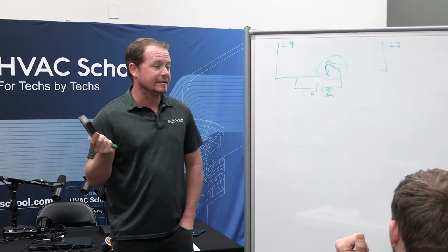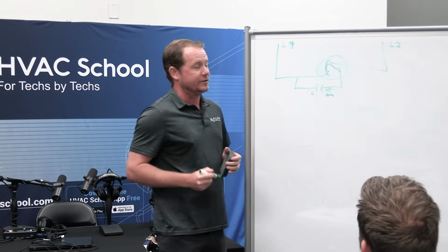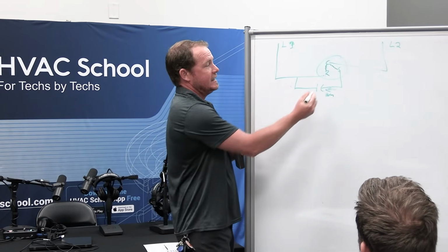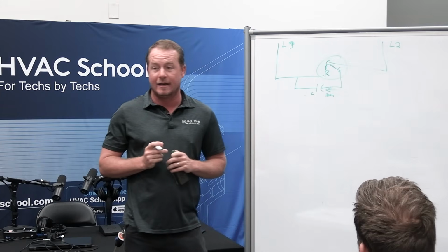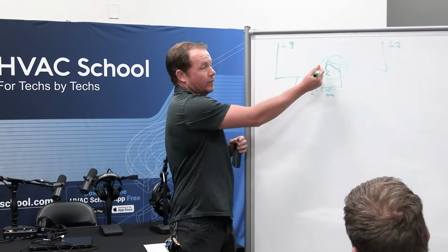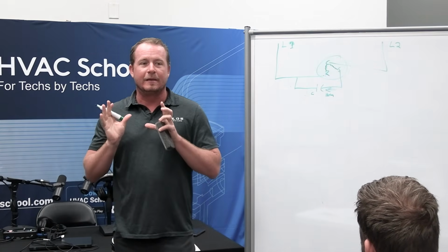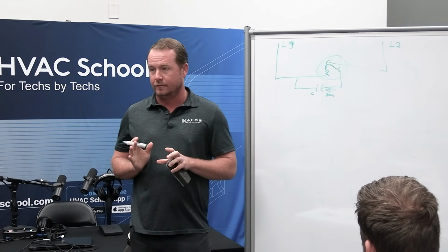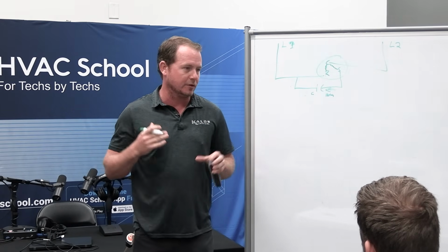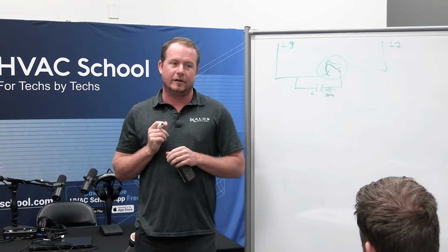But that heat is not going to be where we imagine. Because we imagine if our run capacitor is too small, that it generates heat in our start winding. That's what we imagine. But that's actually not true. It generates heat in our run winding. So if you've got a compressor that's having a hard time starting, you walk up to it, it's not starting. What's that thing doing?